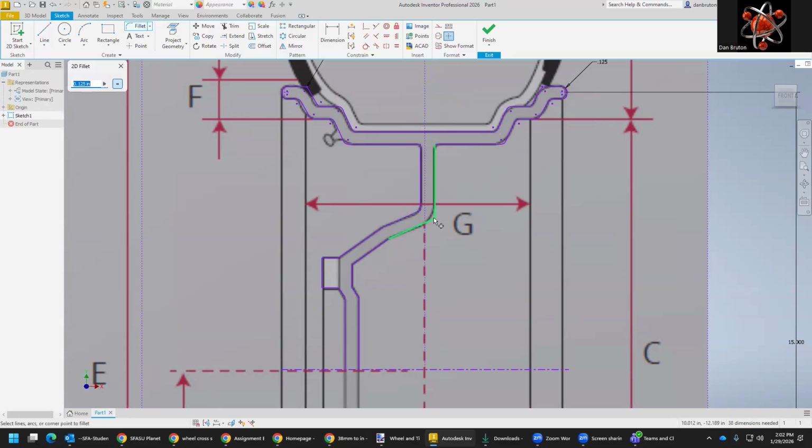Adding a fillet here is probably a good idea. And right here. Now, just because that fillet looks a little bit more extreme, I wonder if we could just double click on this and can we say make that 0.25 instead? Well, I kind of messed everything up when I did that, though, right? Went a little bit extreme. So I'm going to Control Z and see if I can do it beforehand. Like if I put 0.25 here and then say it right here, does that shift it? Not so much. Does it look closer to it? Yes, but does it need to be more? Probably. So I'm doing a fillet.